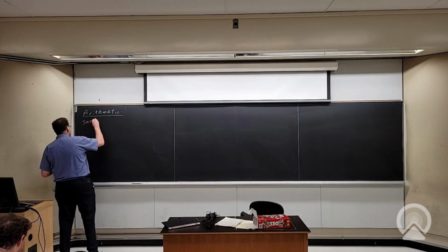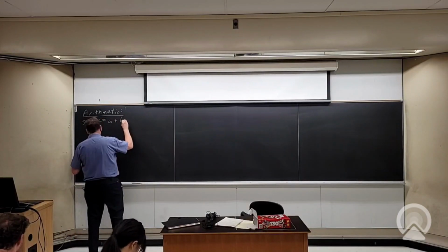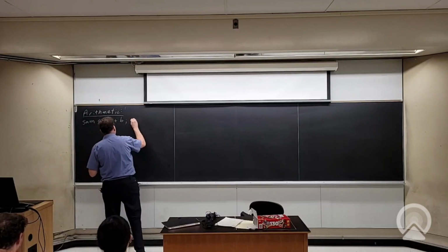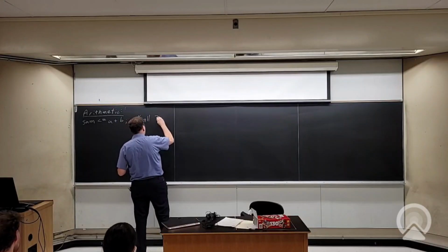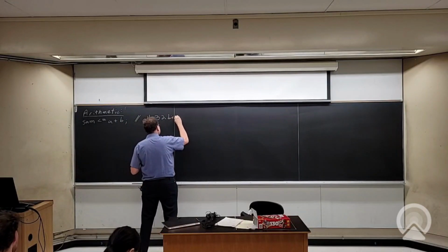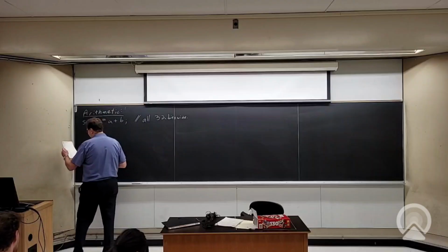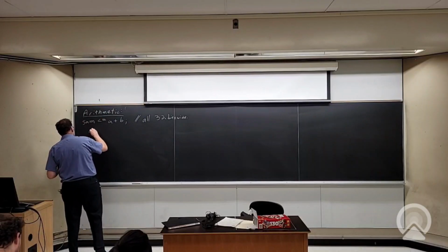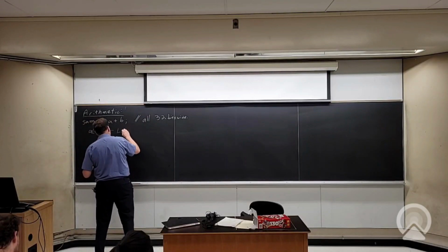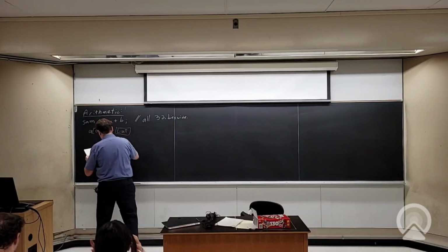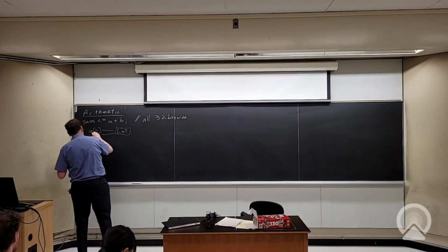Let's say we want to do sum becomes A plus B. These are not 1 bit wide. For arithmetic, usually we're working with wider words, so we'll say those are all 32 bits wide. Let's build that out of LUTs. The structure looks like this. I'm just going to build a ripple carry adder out of LUTs. I've got A of 0, I've got B of 0.